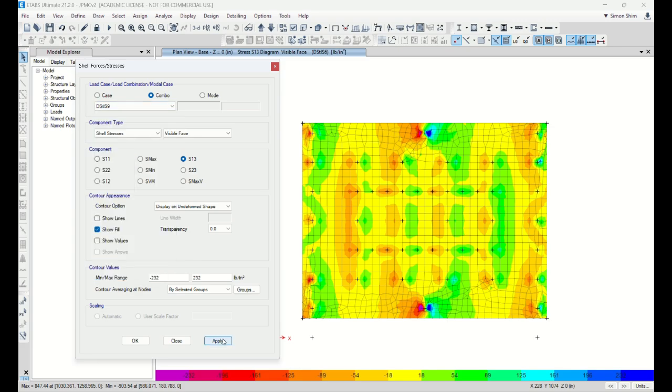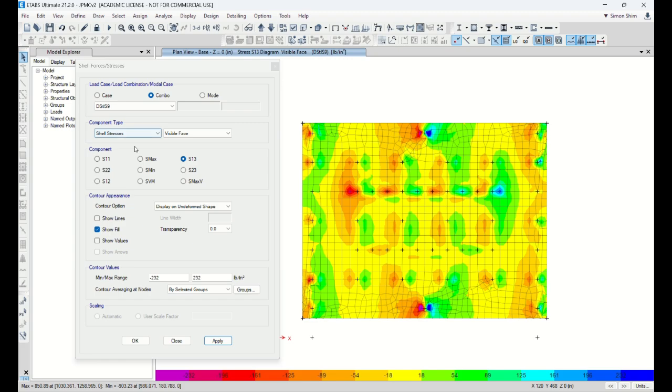But you could also check all the load combinations, the gravity effect and the combination of gravity and lateral effect, and you need to check where the critical shear stress is occurring. We have to decide: if this is too significant, you need to start considering increasing the mat thickness.